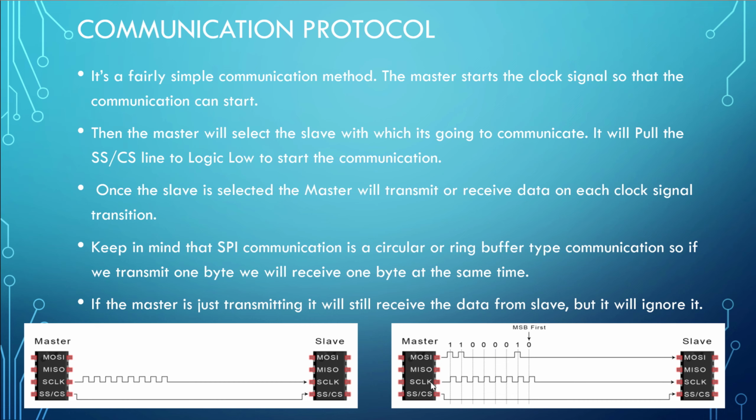And here you can see, for example, if we have set the active high state, which is mode 0, then upon every clock signal high state, it's going to read 1 data bit. So here you can see that when the clock is rising, you can read 1 data bit. Similarly, if you are in mode 3, whenever the clock is going to logic 0, you will read a data bit around here. So it's just 1 step difference, and you don't need to confuse yourself with this.